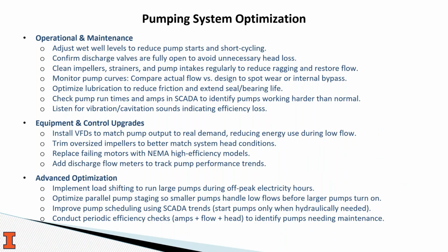Optimizing parallel pumping systems so smaller pumps handle low flows before larger pumps can also help reduce energy use. SCADA can assist with these complex processes, so implementing SCADA is another opportunity to improve pumping efficiency as well.